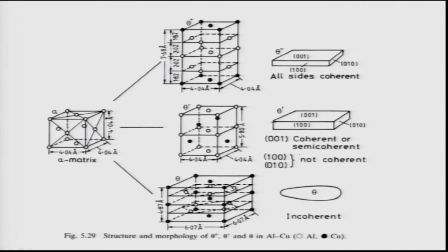So, therefore, the transient phases help us produce different kinds of interfaces between these phases and the matrix. This is what I told you also. And some of the microstructures are shown again because this helps you to understand. GP zones are basically extra 1 or 2 layers of copper atoms on the aluminum 100 planes. So, therefore, they lead to a strain matrix, which is shown here.